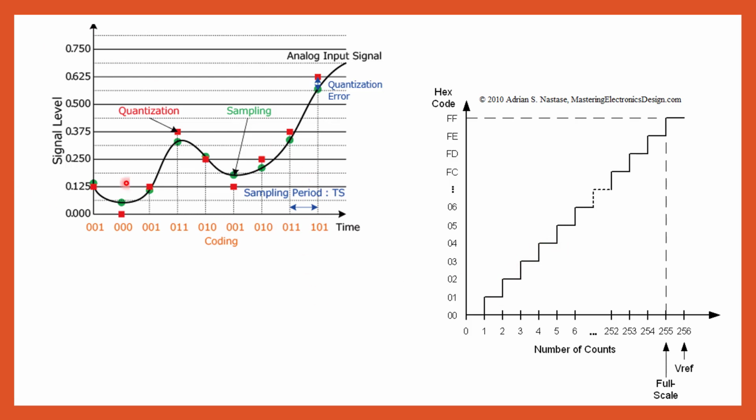Now, what we're doing over here is called quantization level. And in this process, we're decreasing the height, the rise, of these steps. In a sample rate, we're dividing up the time axis, the x-axis, the horizontal axis, and with quantization level, we're dividing up the y-axis, the vertical axis.